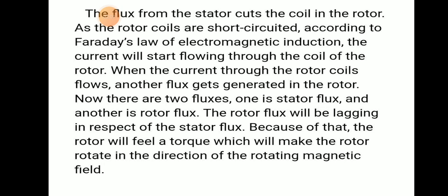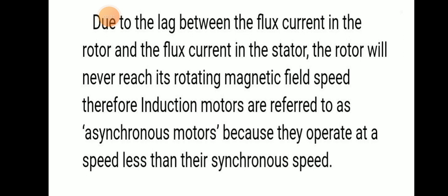This rotor flux will be lagging with respect to the stator flux. Because of that, the rotor will feel a torque which will make the rotor rotate in the direction of rotation of the magnetic field. And due to the lag between the flux in the rotor and the flux in the stator, the rotor will never reach the rotating speed. Therefore, these induction motors are referred to as asynchronous motors because they operate at a speed less than the synchronous speed, and they can never reach that speed. That means they will always be operating at a speed less than synchronous speed.